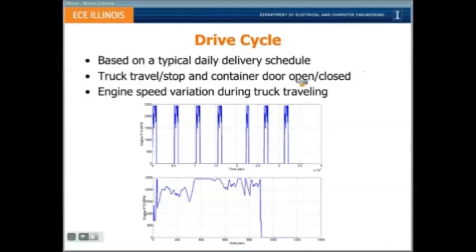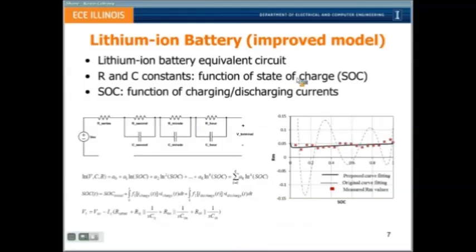Yeah, that's a very good point. The lithium-ion battery model is a little improved from the previous model. It's modeled like this: internal resistance and some second-, minute-, and hour-scale RC models, which come from the capacitive effect inside the lithium-ion battery. And these RCs can be tested.